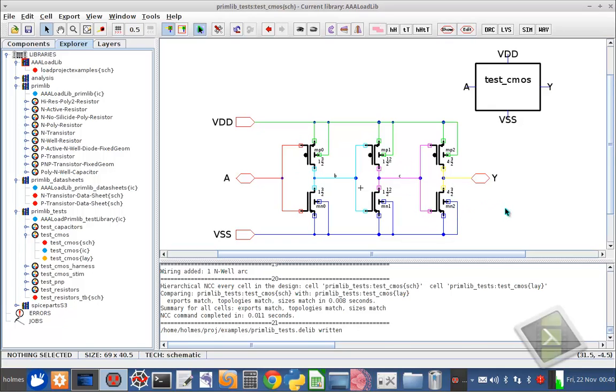Those are just some handy things to keep in mind when you're analyzing a schematic or you're getting strange results. A lot of times it's because something is either shorted or floating, and those checks show very clearly that things are connected properly. If they're not connected, you won't see these little colored boxes floating around the ports. Those little box halos will not light up. So it's a great visual inspection tool for looking at schematics and how things are connected.